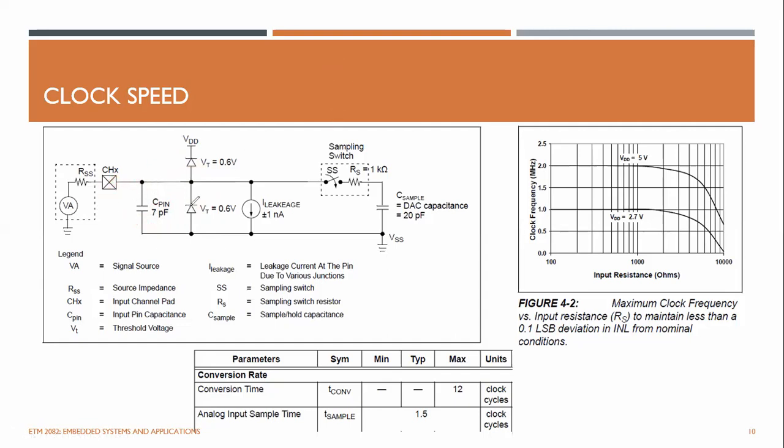In the absolute maximum ratings, I have shown you that this voltage should not go below minus 0.6 volt, and also should not go beyond VDD plus 0.6, because these safety diodes can protect your pin from any voltages within this range. If it goes beyond that, they can protect to some extent, but it cannot be guaranteed.